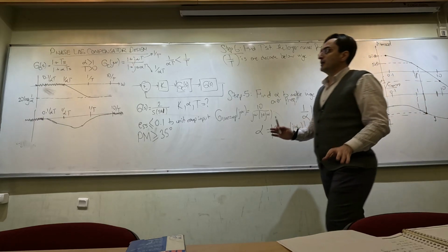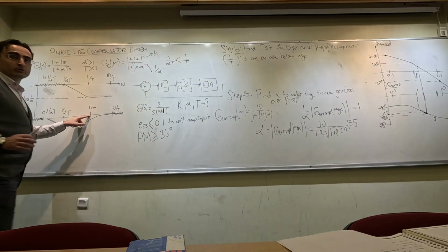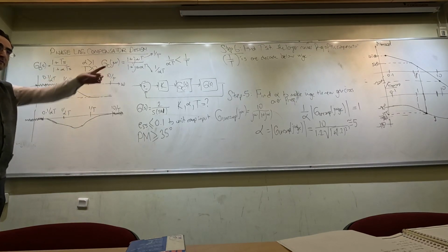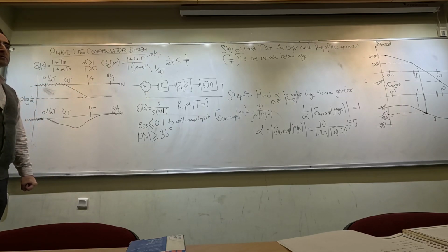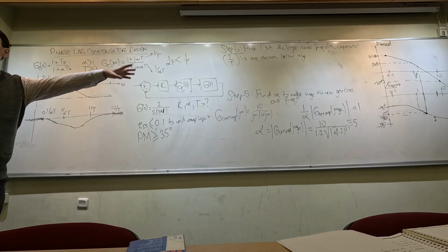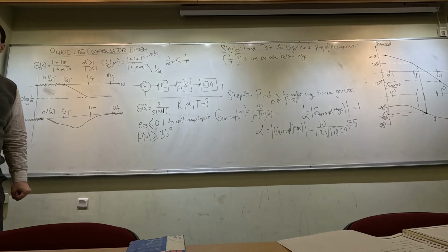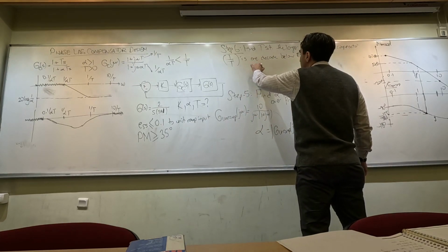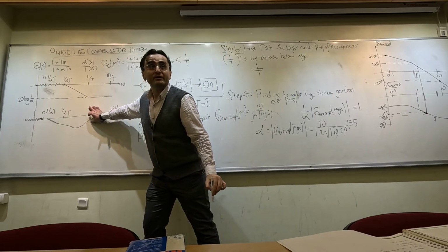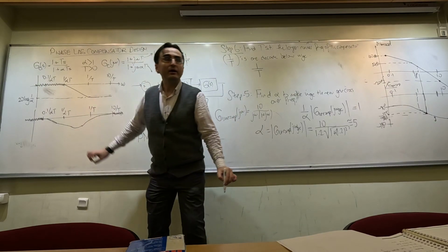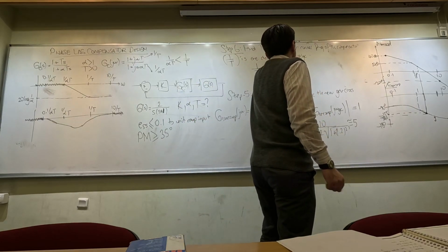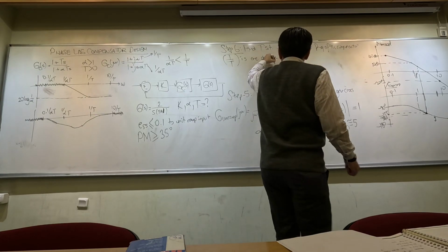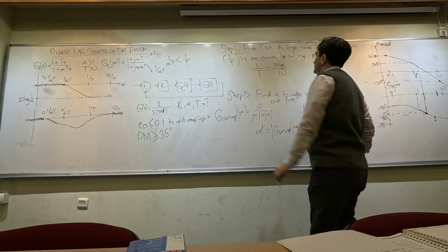That means that I'm going to try to place this corner frequency at least to a value which is 10 times lower than the new gain crossover frequency. So I need to place 1 over T, this frequency where this phase is non-negligible here, at least to a value which is 10 times lower than omega GC. So I'm going to place it like this.